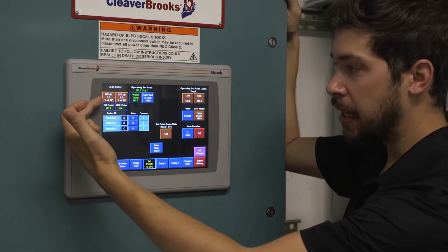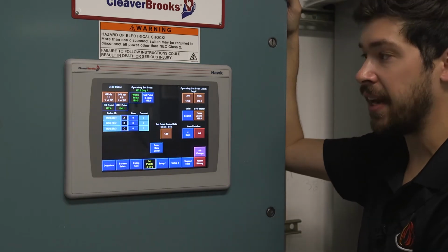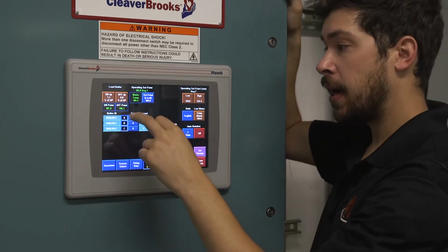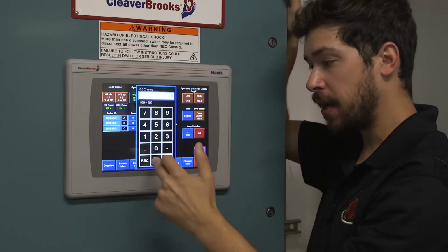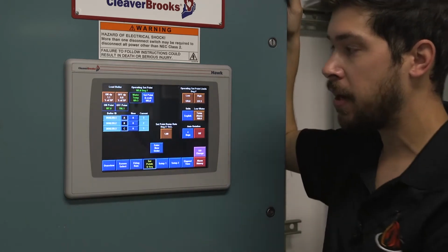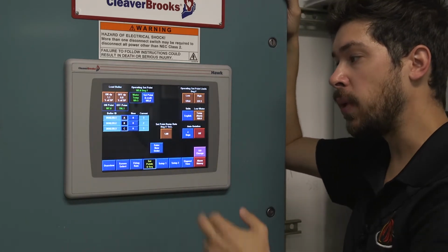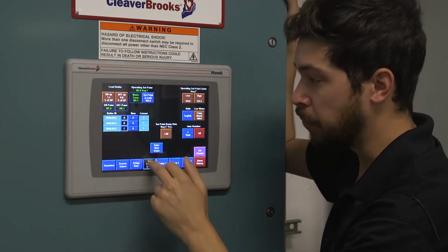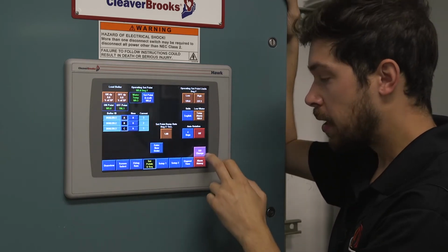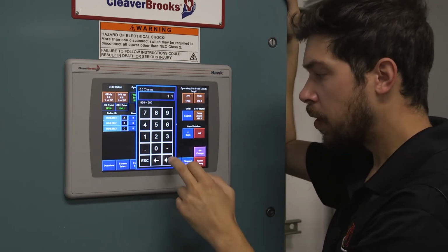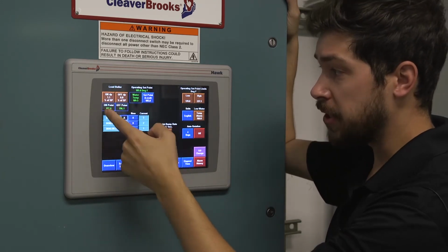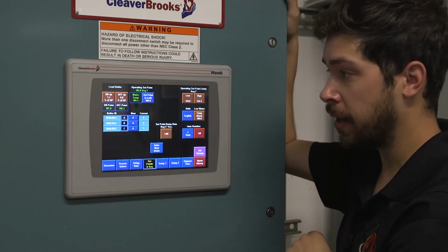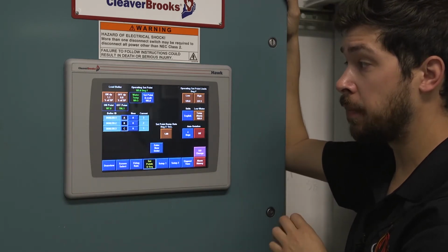So really, this number here should never go negative. It's the same process of hitting the purple dot and pressing the button to change these numbers. But we don't hit the purple dot and say 187 and then bring it to the brown box. We say 1.1% of the local set point. That's what I want the on point to be.